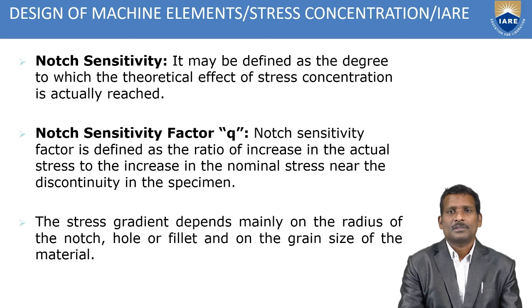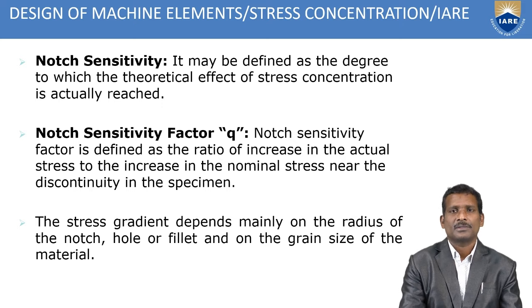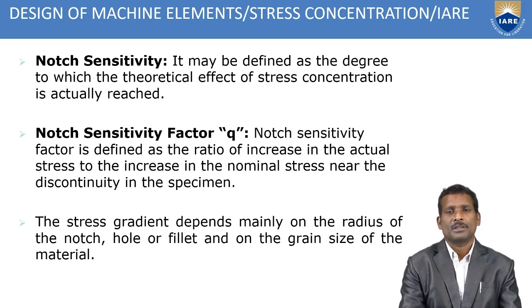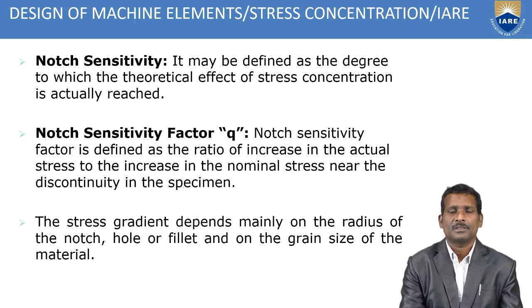So next, the notch sensitivity. It may be defined as the degree of sensitivity at which the theoretical effect of stress concentration is actually reached. Suppose any object is subjected to load, then stress concentration occurs. We consider the stress concentration while designing, so there you have to measure the notch sensitivity. The sensitivity means the sensitivity of the component. Clear? So that's the degree, in other words, the magnitude of the stress concentration.